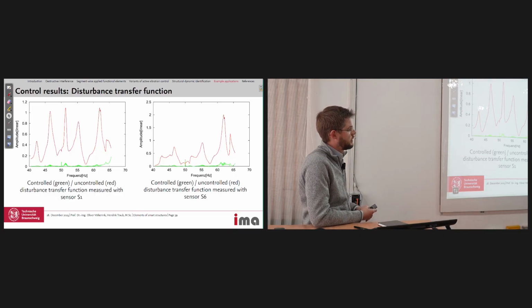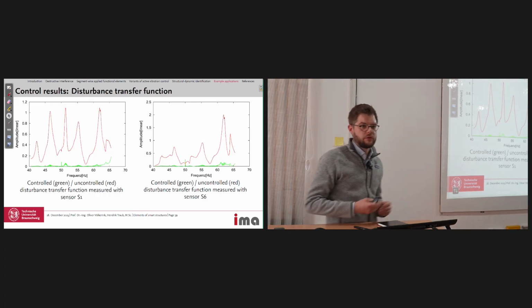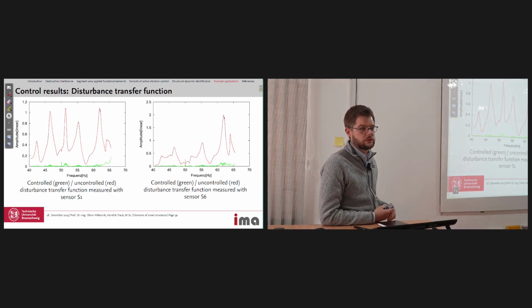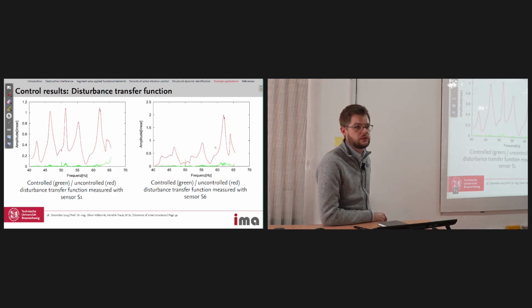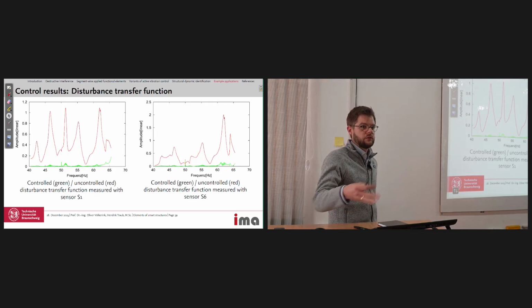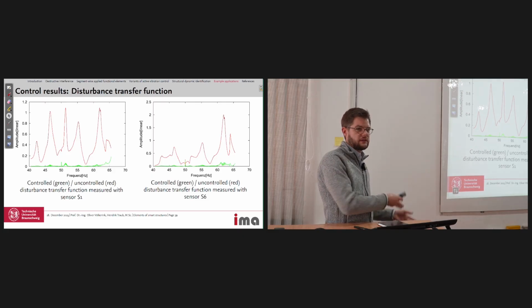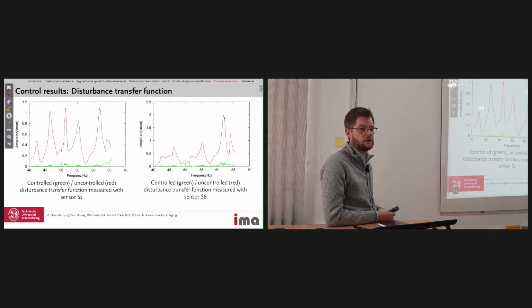I mean, you can perform finite element based modal analysis if you have a model of your structure where you want to suppress the vibrations, and from the modal analysis you know the eigenfrequencies as well as the amplitudes, and then you can select the eigenmodes you want to suppress. I think it depends as always how close the model is to the real structure, but at least if you have a model initially, then that should be possible.